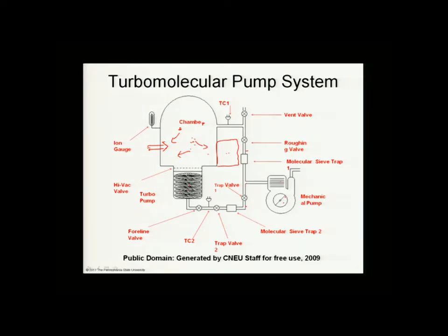The ion gauge, because this is where the low pressure is going to be. This is going to be the high vacuum or ultra high vacuum region. The thermocouple gauge for when you're beginning to pump there, and you can see here the pressure should be relatively high because the mechanical pump is pumping on what's coming out of here, the effluent, so you can use a thermocouple gauge there, and as I said, all the necessary valving to be able to do what you want to do when you want to do it.